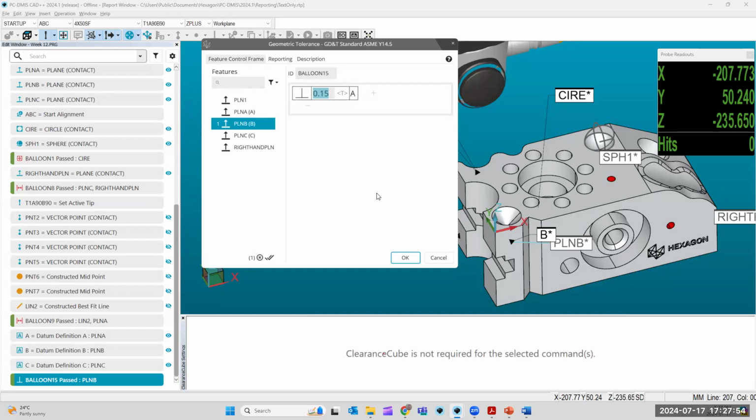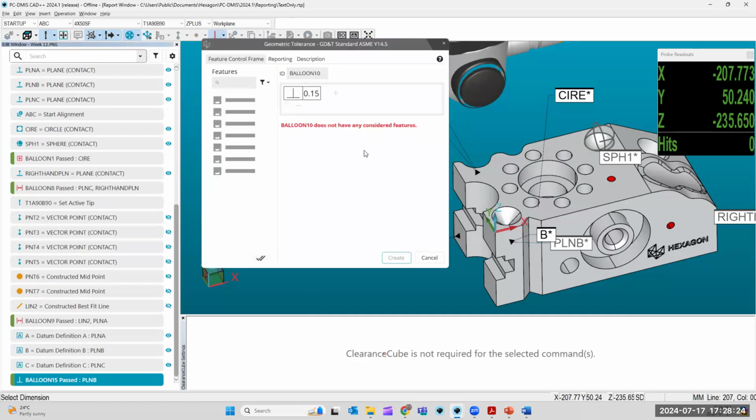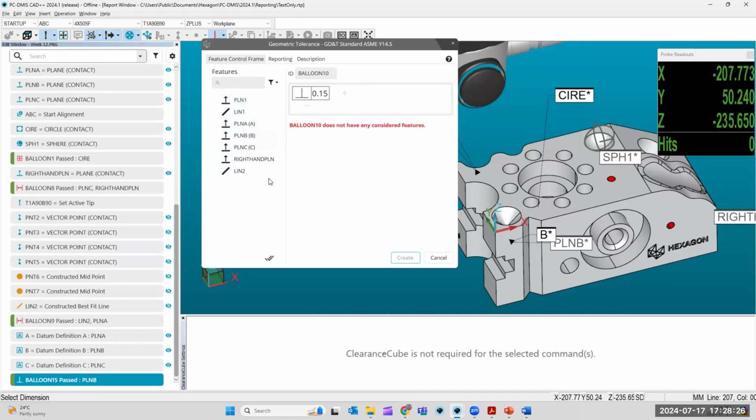What I would do if I was trying to check perpendicularity quickly with the part someone handed me, I would mount it on my machine. I would take my joystick. I would make a plane. I would hit point, hit the check mark. It built a plane. Plane's a 3D feature. Then I check the secondary plane, so I hit point on my second plane. I now have plane 1, plane 2. And all I'm going to do is say, okay, what's my perpendicularity between plane 1 and plane 2? So plane 1 with reference to plane 2.